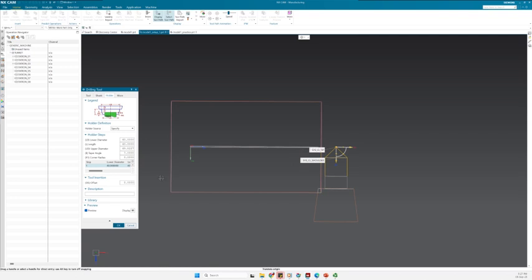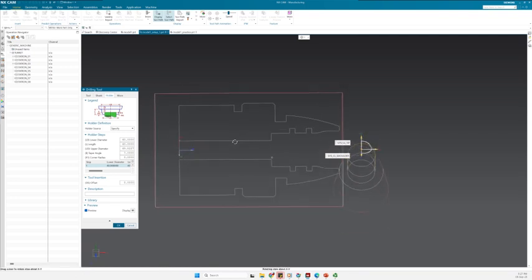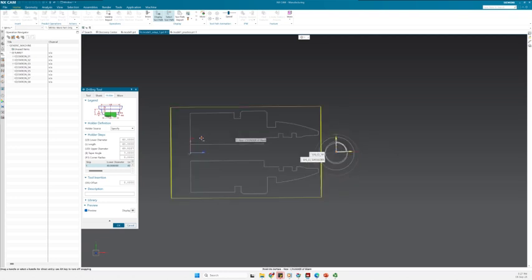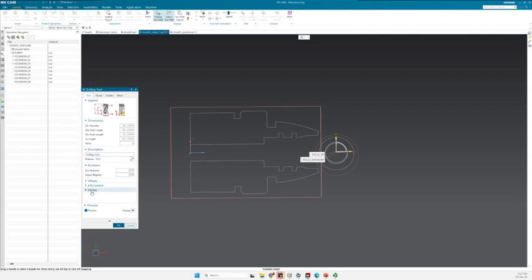So for example, this is my spot drill now. I don't define it fully for the sake of this tutorial so that we save time on the video. Now, supposing that we are defining the size of the tool holder and also the shanks and so on, and hoping that the values are correct, we can see that the tool number is 2, it is correct, and then you have some other information, or you could actually retrieve it from the library as well.